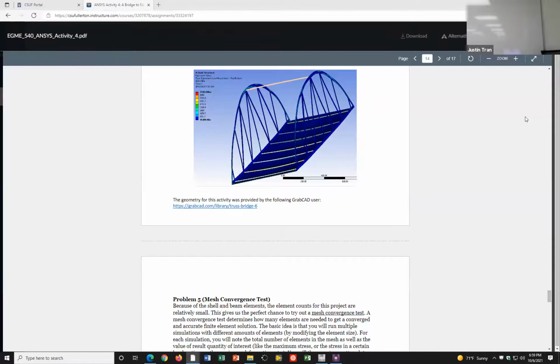Is this right? Because before I had the contact and the target switched. Yeah, there was a question. For the contact and the target, it seems like it shouldn't matter, but it actually does. The target should always be the bigger of the surfaces. Since this is the bigger one, you should have that as the target, and then the contact is the same. If it detects that, I don't know why it just doesn't switch it automatically, but you can switch it. Is there anything special on the machine here? Not particularly.